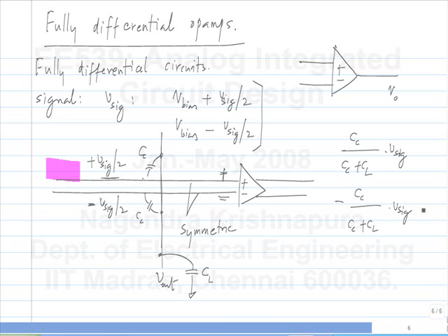So if you process a signal differentially, it is immune to interference that is injected upon it. It is also going to inject less interference because you have a pair of wires, each carrying equal and opposite signals. So if you have some other wire, from these two wires, the interferences will get cancelled out. Okay? Again, assuming physical symmetry and so on. So it is more immune to interference and it also puts out less interference. Okay? So the best thing is to make everything differential so that you have very little interference going around. And what little common interference there is will get cancelled out because you are going to process the signals differentially.